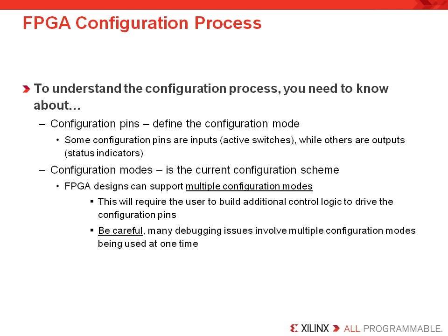The configuration pins each have their own purpose. Some are active switches, that is, inputs to the FPGA, while others are status indicators, or outputs. Understanding their roles is the first step if the user is going to debug their own configuration problem. The configuration data stream is a little more complex, but understanding it is important if you are going to debug your own configuration problem. Note that configuration problems usually occur when the user is building a scheme that includes multiple configuration techniques. This is not especially challenging, but is a necessary byproduct of a designer, quote, doing it himself.